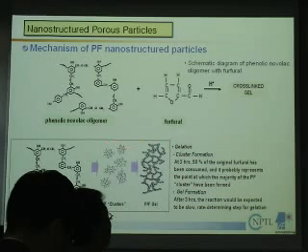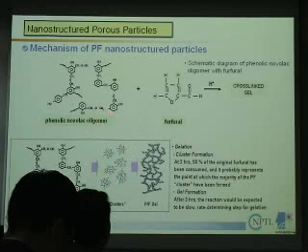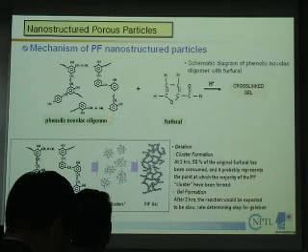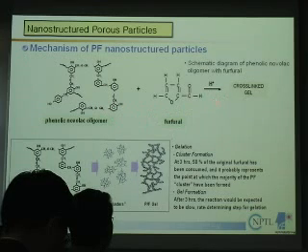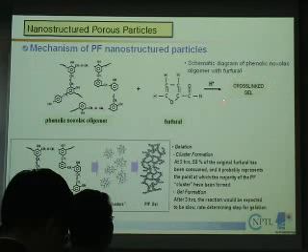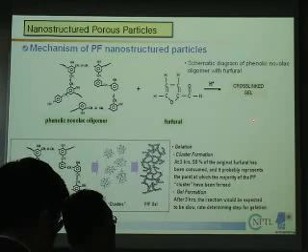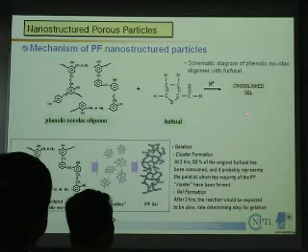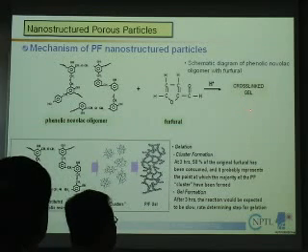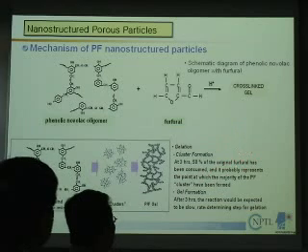For that, we chose standard network-forming polymerization using phenolic oligomers with an acid catalyst, and you make a gel. Then you have to exchange the water with acetone, and then extract the acetone using the supercritical fluid. You finally make this kind of aerogel.